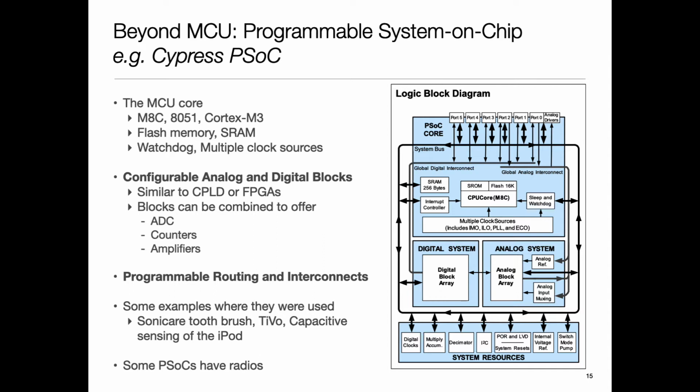Could you quickly explain why chiplets might be preferred over just buying the IP, the RTL, and putting them all on something? Sure. I think I failed to make that point convincingly. If you purchase IP blocks, the designs, and put them all on the same silicon, the issue still is what semiconductor process do you use? The process which is best optimized for memory may be different than for your radio, may be different than for the processor. So you have to compromise, whereas the chiplet approach basically lets you use the best.